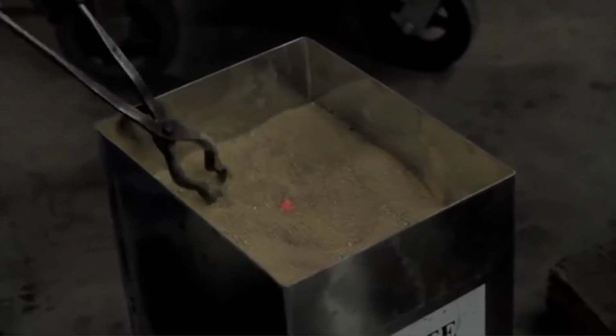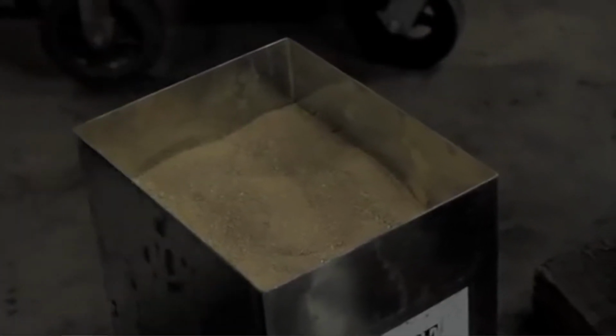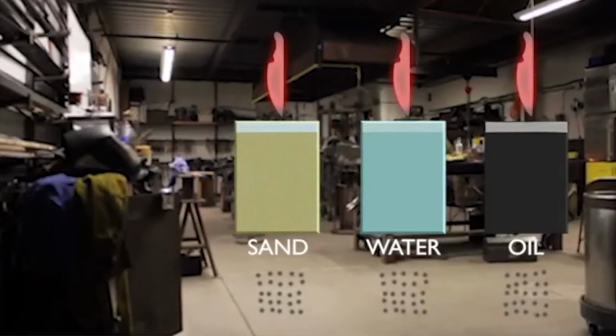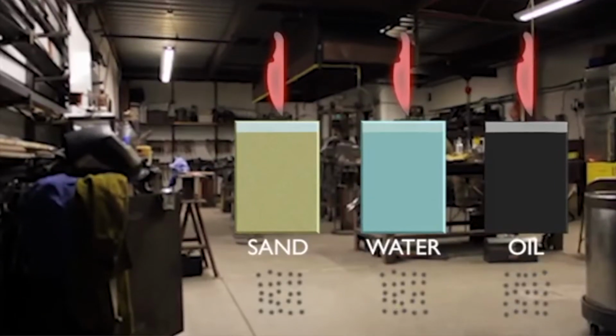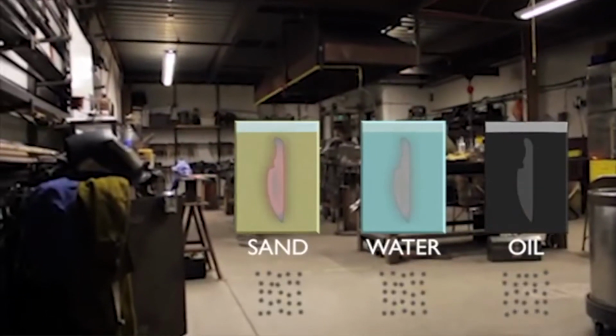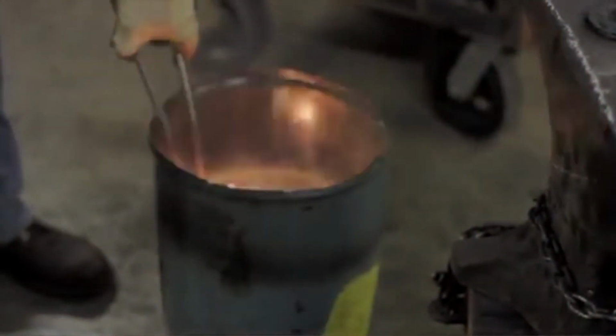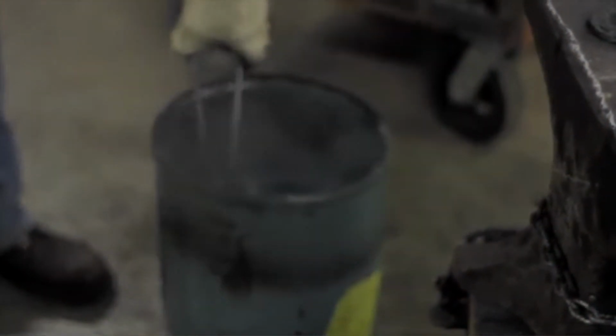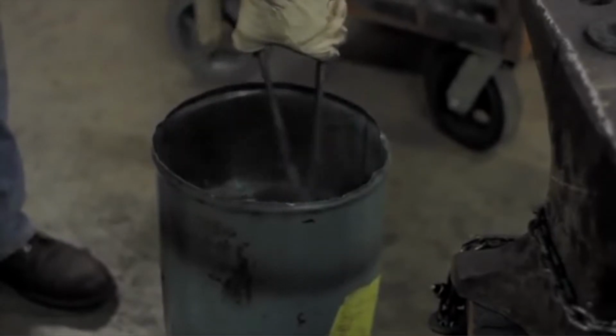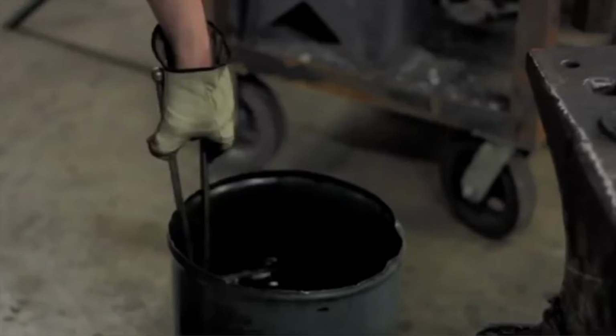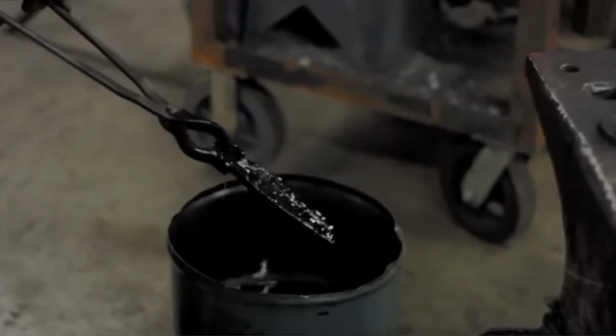Right after the austenitization, the austenitized rods are quenched into oil. This process will significantly affect the microstructure and the final properties of the material, so it must be controlled. The quenching process first involves oil quenching the steel down to roughly 540 to 595 Celsius in a matter of seconds, then normalizing the hot steel rod to ambient temperature over an hour.